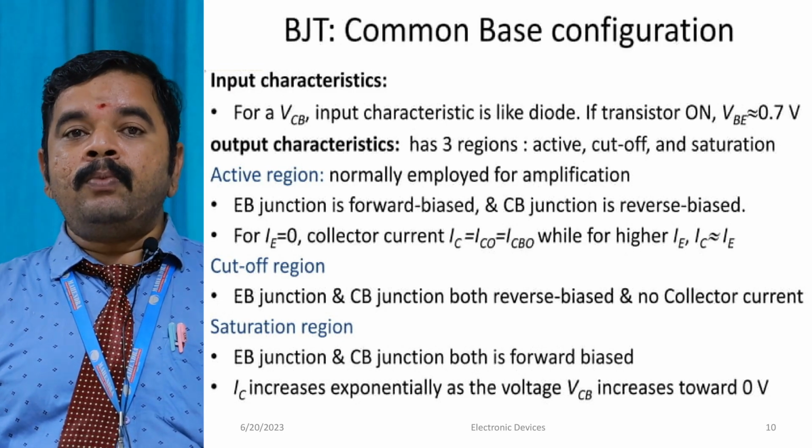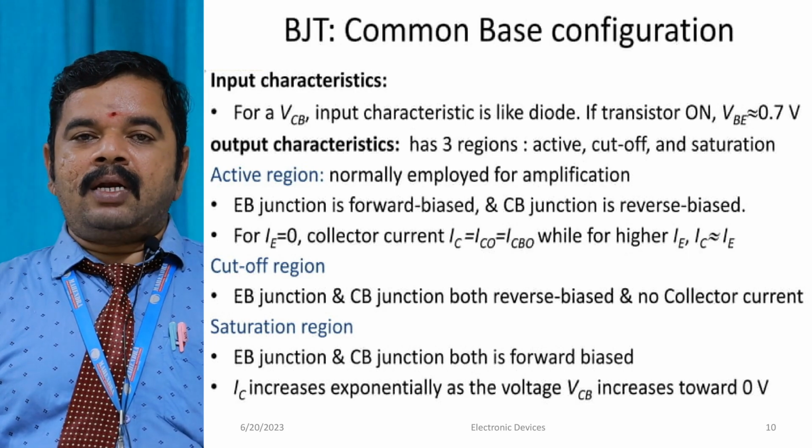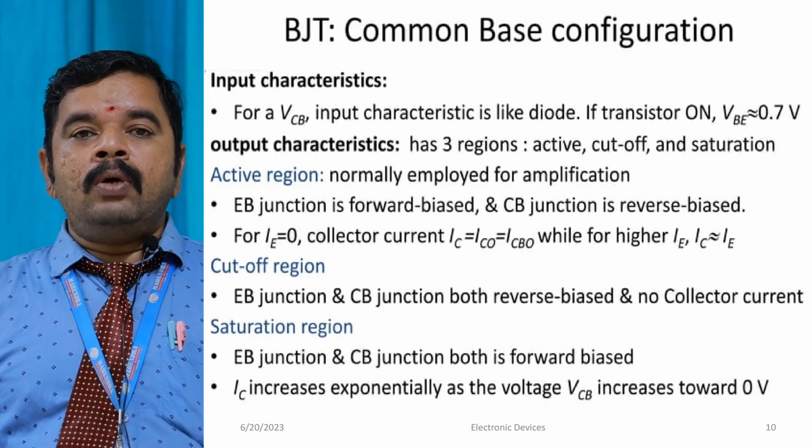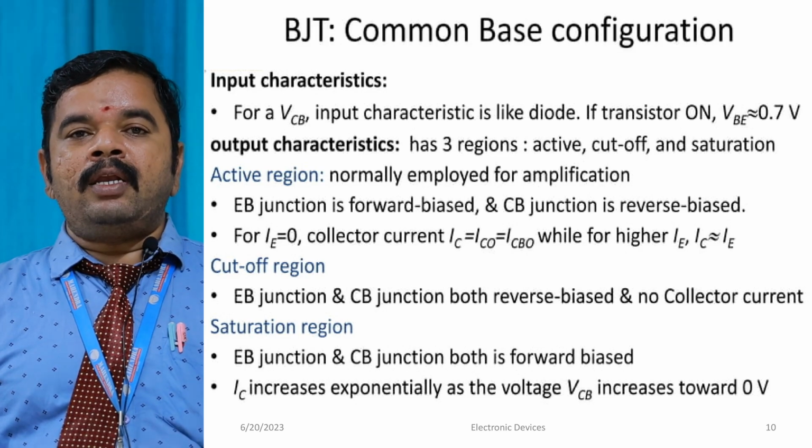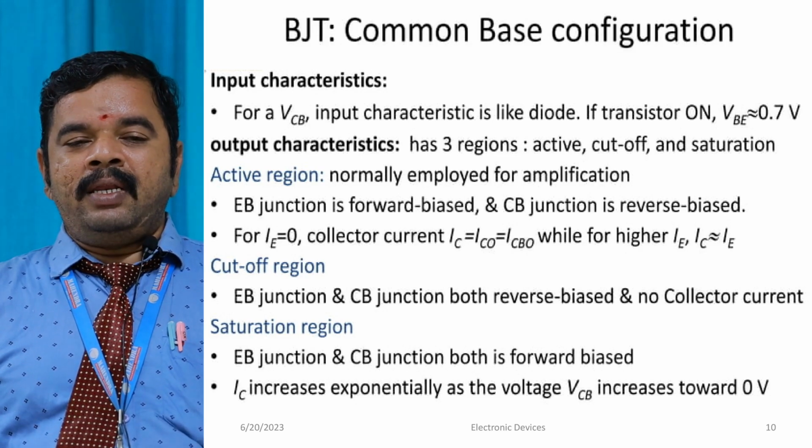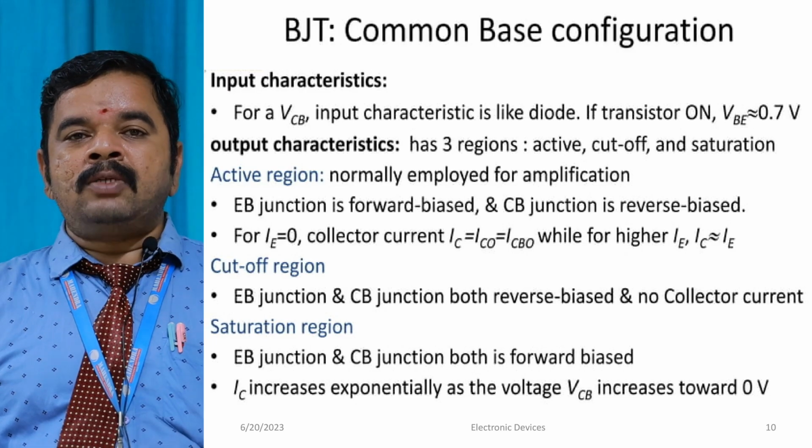What does the saturation region mean? Both regions, the emitter-base as well as the collector-base, the input side as well as the output side, will be in forward bias. While it will be the linear region, in the second region the current will be linear. So what is actually linear?